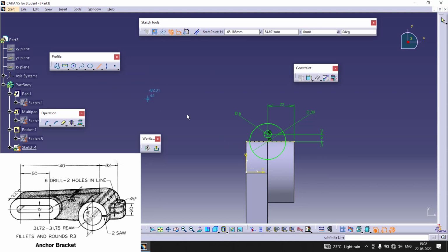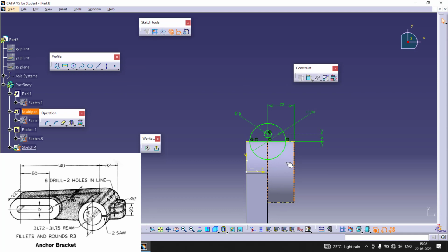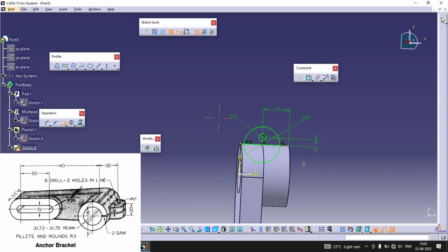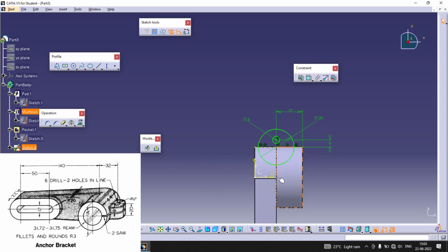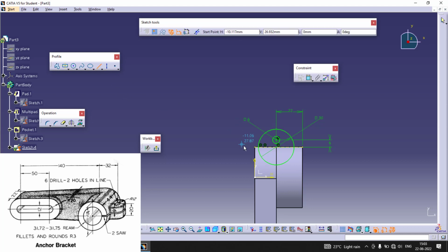But I cannot extrude it from the center, so this doesn't work because this is the curved surface, so I can't extrude like that. It has zero thickness and extrudes inappropriately as a boss extrude. So I'll take it slightly inside. I can use make normal to plane, sketch plane, if your sketch is oriented a bit somewhere.